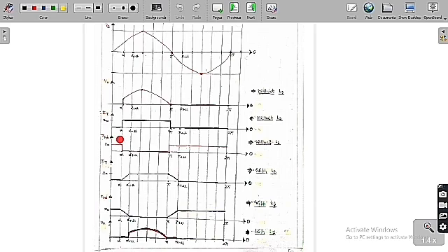We have assumed that the load current is a constant current, because the load is assumed to have a huge value of inductance. So from alpha to pi, the thyristor is going to conduct, with the thyristor current equal to the load current, I naught. Whereas from 0 to alpha and pi to 2 pi, the freewheeling diode is going to conduct. So this is the diagram of the freewheeling diode current, which is I naught here and here also I naught. So these are the graphs of the output voltage, thyristor current and the freewheeling diode current without any source inductance.